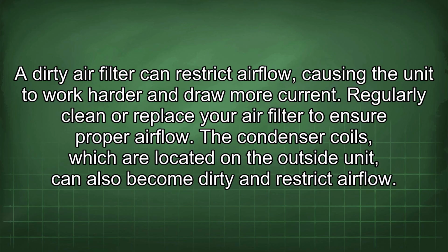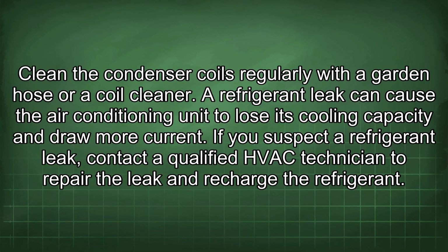The condenser coils, which are located on the outside unit, can also become dirty and restrict airflow. Clean the condenser coils regularly with a garden hose or a coil cleaner. A refrigerant leak can cause the air conditioning unit to lose its cooling capacity and draw more current. If you suspect a refrigerant leak, contact a qualified HVAC technician to repair the leak and recharge the refrigerant.